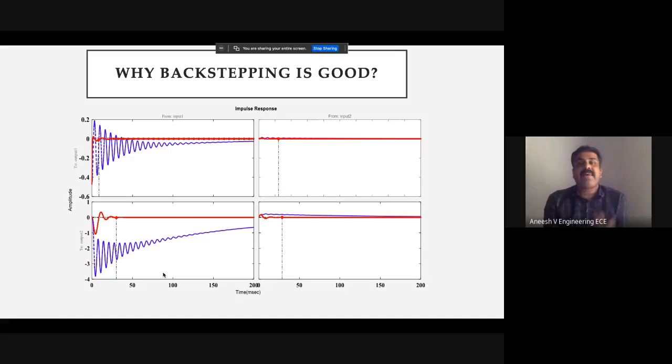This is a comparative analysis of an aerodynamic system, a Boeing 737 flight. That means input 1, input 2, output 1, output 2, based on pitch, roll, and yaw formation. We designed this particular backstepping technique for the controller. It is a multiple-input, multiple-output system.